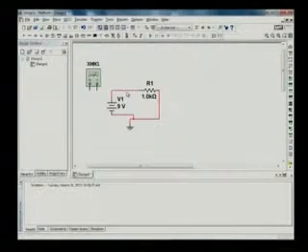So what I will do is I will delete this wire. To delete it, you just click on it, and that junction wire will show blue squares. That means you have selected that line, and you just have to delete it, right?